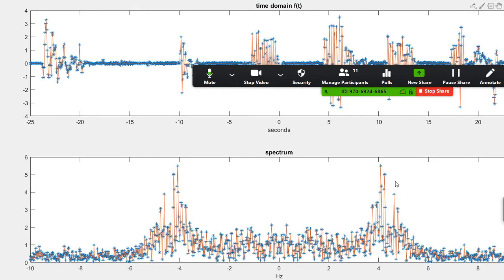So for the gyroscope, you can see the movement frequency is all around 5, and there is no DC component. Why no DC component? Because the gyroscope does not sense gravity, so gravity has no influence. Their DC component is 0. So this measures the AC component. And I also can generate another.